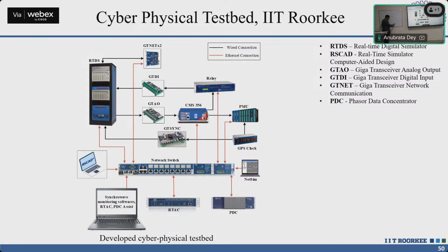Now these two sets of data, you cannot acquire at the same time instances. Whatever data you acquire here at some time, let's say t1, there has to be some time difference, t2, for the other. Since t1 and t2 are not the same, this is known as unsynchronized measurement. But your PMUs acquire the data at the same time instances, which is known as time stamping.